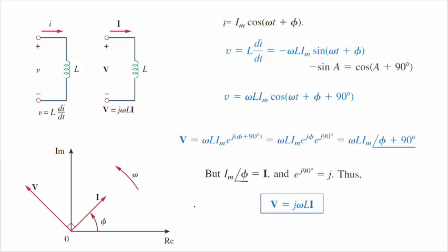What that means is that in a circuit, when I is a max, V is not a max. If I put it on the real axis, you can see that. I'm going to show you an example to ensure that you see it. So the point in time where I is a max is not the same as where V is a max, like in a resistor.